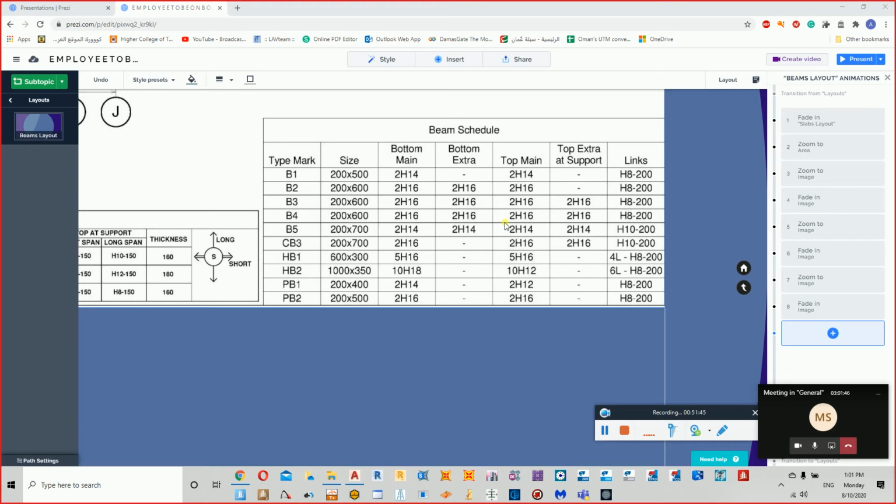If it's not sufficient, it's sufficient for the sides because they have lesser bending moment. For the peak, because of the parabolic, the maximum is at the center. Now we need to supply extra reinforcement if it's not sufficient. The same thing for the top, extra reinforcement, and the curvature goes like this. So we have smaller values here, extra, or the peak is going to go here.